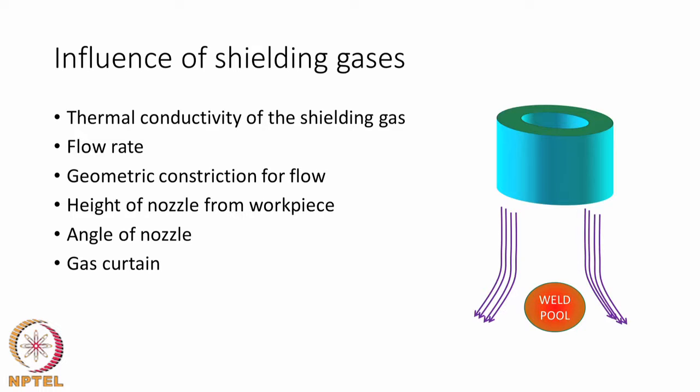And usually the welding processes are such that the flow rate is not varied much, because the purpose of the gas is only to shield, and it will be kept constant for most of the welds. However, if there is a change in the flow rate, then we must know and keep that information handy to modify the heat source as the case may be.